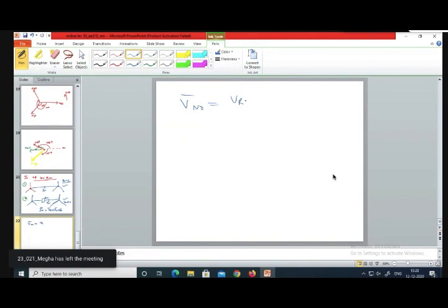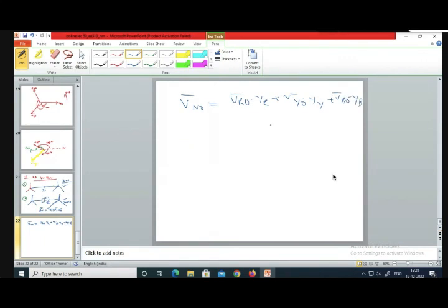Here it is VRO into YR plus VYO into YY plus VBO into YB, divided by YR plus YY plus YB. And one more thing you have to add is the neutral admittance, that is YN.